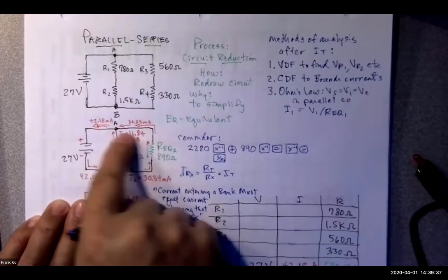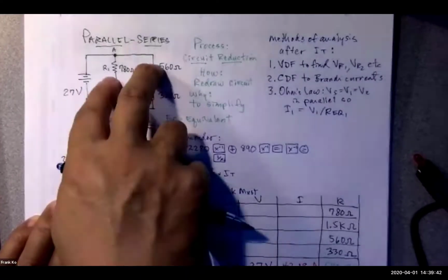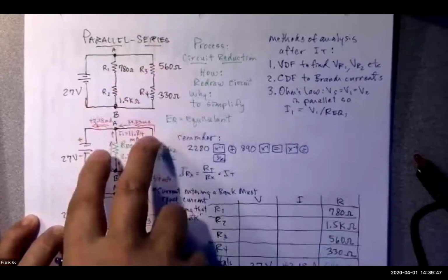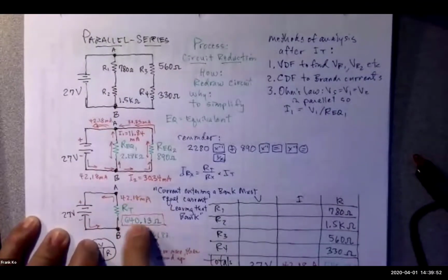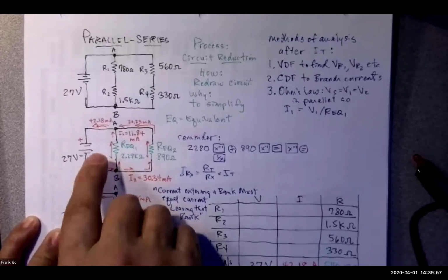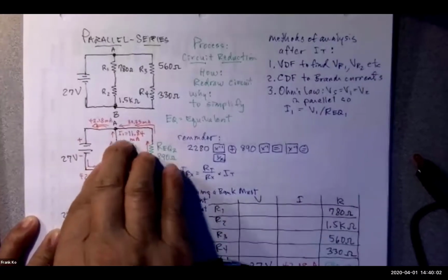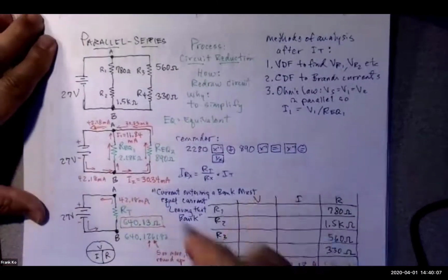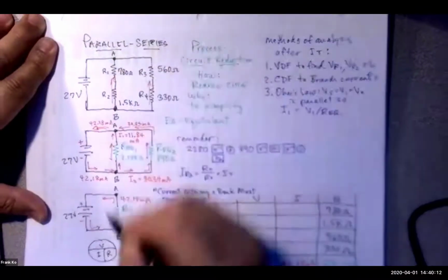And with this analysis, can we now bring some of this information back to the original? We started in our analysis with this, simplified to here, simplified to a single resistance. From here, we found our RT. Here we found our IT. We bring this IT information into the middle circuit. The IT we discovered split. Now we can take this information back up to the original circuit. We now know the current that flows up here, and we now know the current that flows over here.